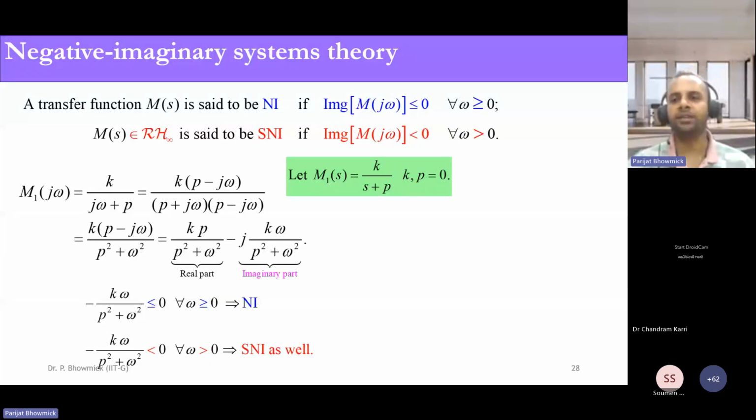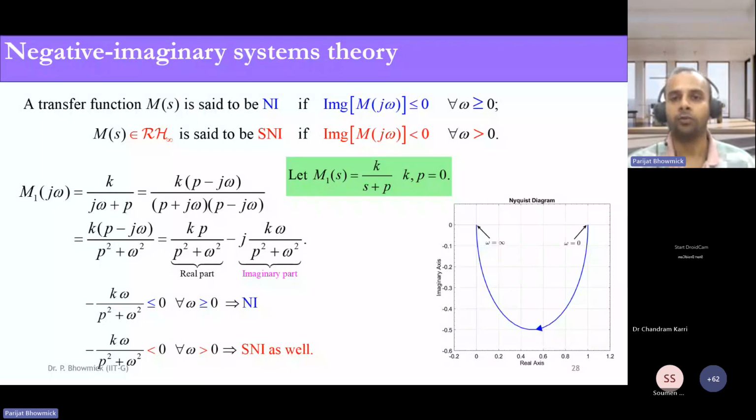This can be easily interpreted by its polar plot. The polar plot is one type of frequency response plot, other than the Bode plot, because the Bode plot, I think all of us know, is simply the frequency response, that is log 10 omega versus the magnitude in dB. Here it's another kind of plot, which is the polar plot. So for the polar plot, you can easily check. Suppose you are given an LTI system, a SISO LTI system, and you see the polar plot.